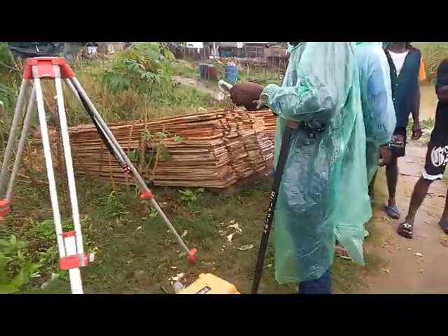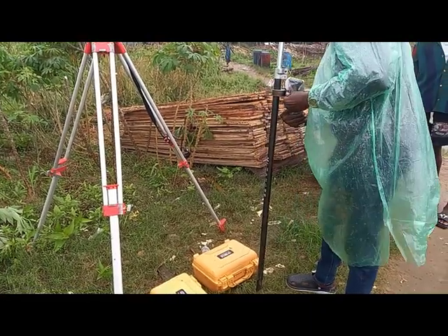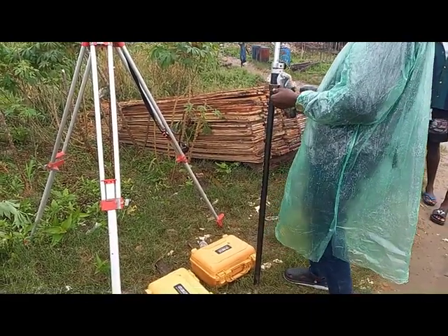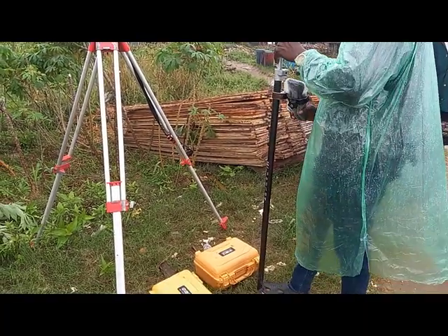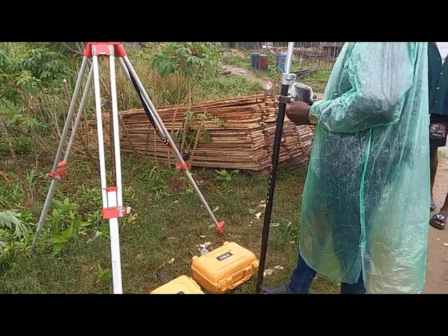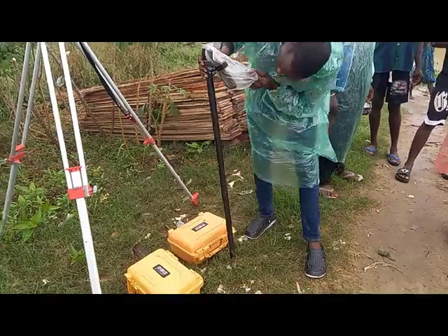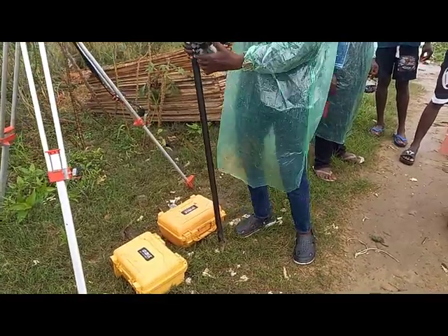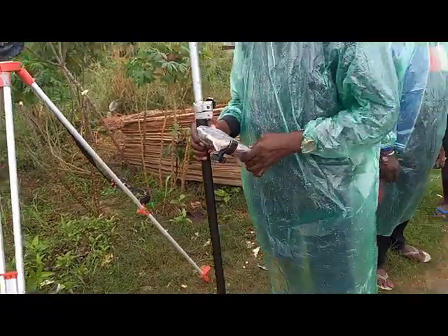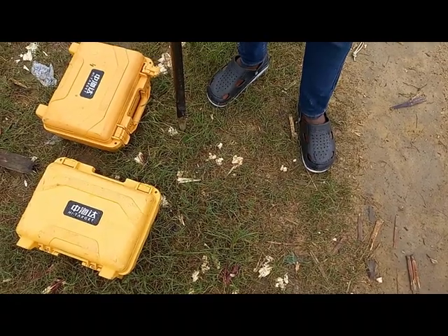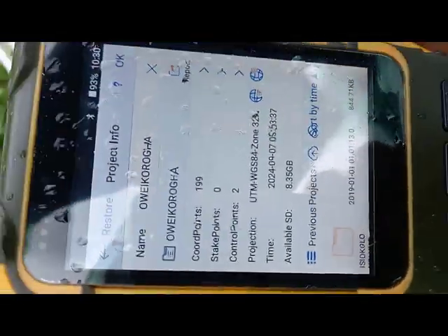Depending on what is being used, that receiver and data collector device is going to be calibrated according to the UTM. You need to calibrate this data collector device in order to synchronize the base GPS, the rover GPS, and the data collector itself. So these three different devices need to be connected. You can see this is a snapshot of what it looks like.